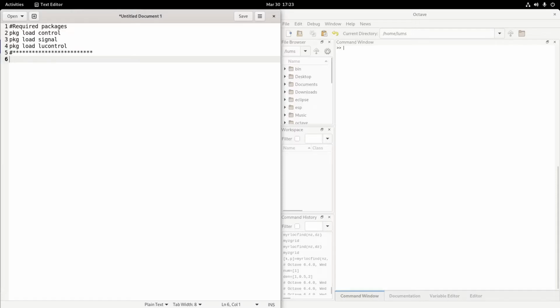And then now we will define the transfer function, the same transfer function which we used earlier. So the numerator polynomial, pretty simple, is 1. The denominator polynomial is as shown below here. And let us plot the root locus. Now this is the transfer function, and plotting the root locus is a simple one-step command.